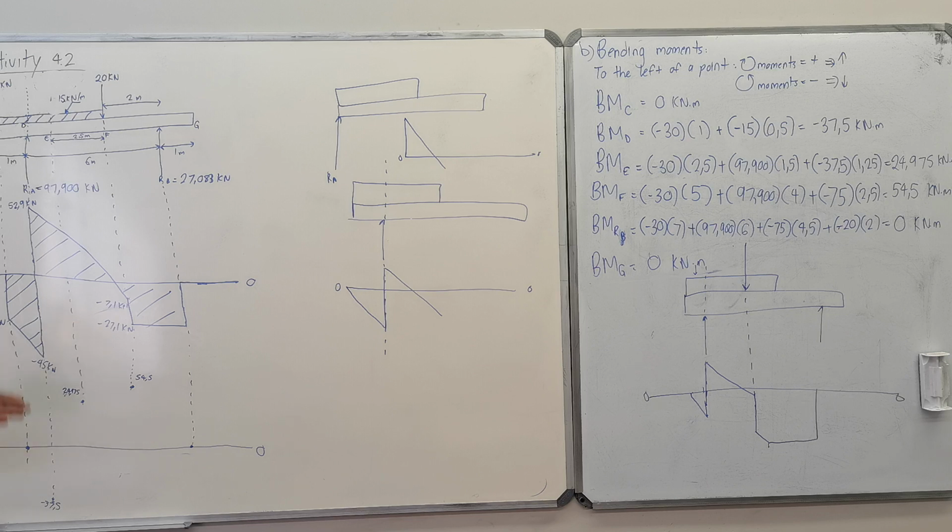So, bending moment diagrams, look at your loading diagram, right? So if you go back to your page 76, right? Wherever a concentrated load acts, it's basically just a point on the diagram. And then the lines between concentrated loads are straight lines, right?